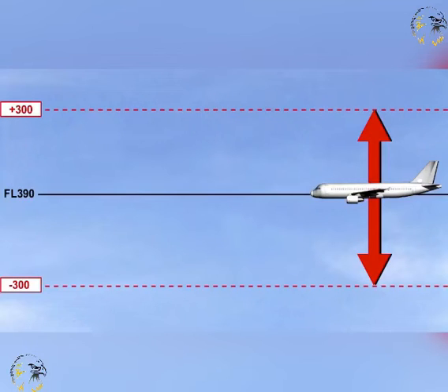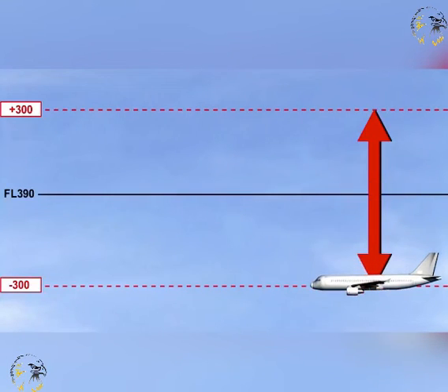An aircraft is deemed to be maintaining a flight level when Mode C derived flight level information indicates that it is within plus or minus 300 feet of the assigned level. When cleared to vacate a level, an aircraft that has a Mode C derived indication of more than 300 feet in the anticipated direction of change is deemed to be vacating it.